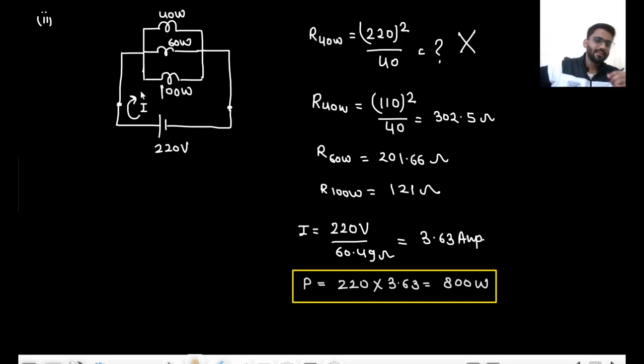All the three bulbs have a strong chance that they may burn out, because all the three bulbs are getting 220 volt, and they only need 110 volt. If you are giving so much supply to them, they have the chance to burn out. And if they are very good, they can take up this much supply, then they will give you much brighter light.